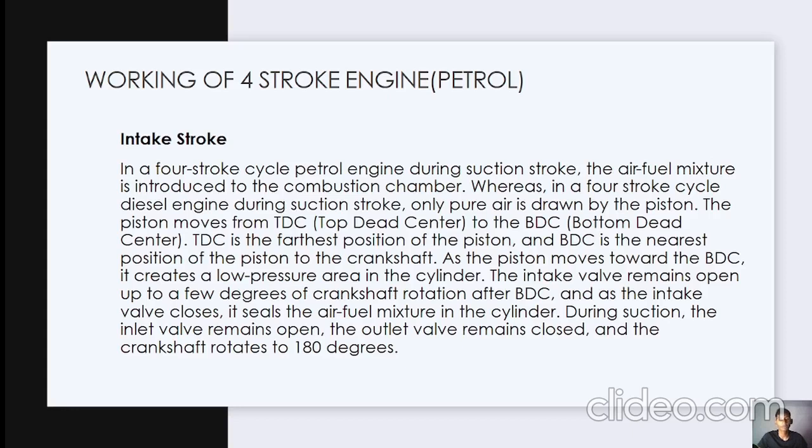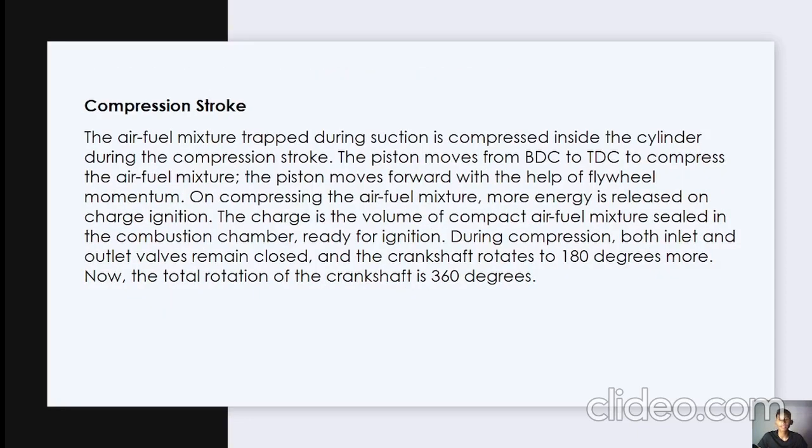As the piston moves towards bottom dead center, it creates a low pressure area in the cylinder. The intake valve remains open up to a few degrees of crankshaft rotation after BDC. And as the intake valve closes, it seals the air-fuel mixture in the cylinder. During the suction, the intake valve remains open, the outlet valve remains closed, and the crankshaft rotates 180 degrees. The air-fuel mixture is compressed inside the cylinder.